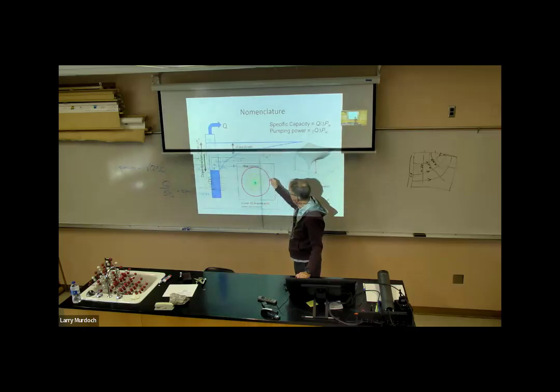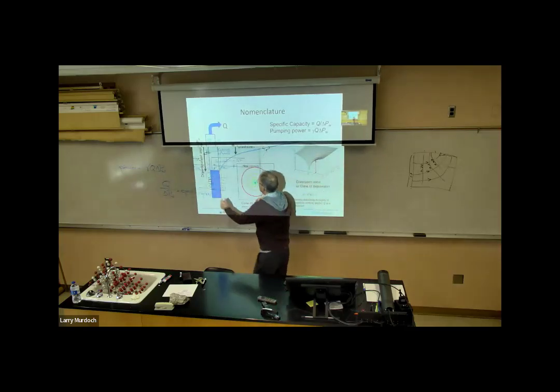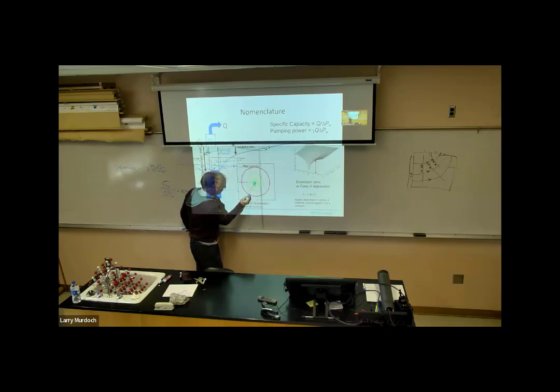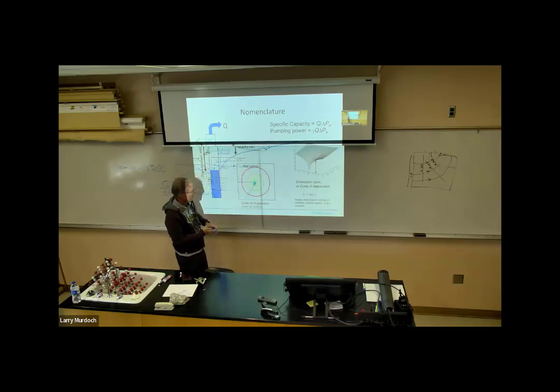One thing we wanted to point out here is if we draw this with flow lines in it, with flow that comes in like that, and flow that comes in like that, they're perpendicular, right? Because we're assuming that it's isotropic. What you get from this is a flow net.